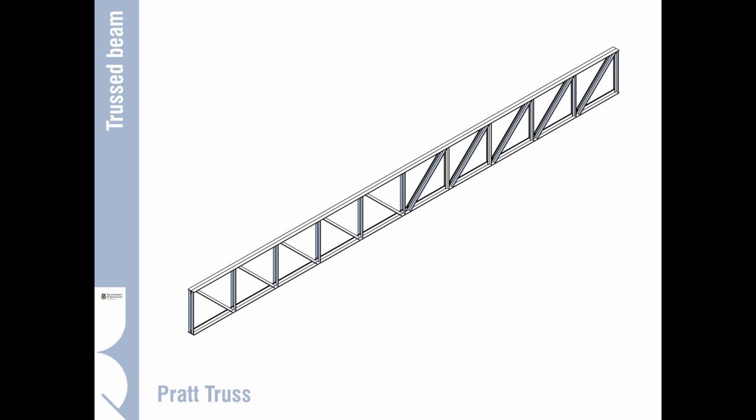As we saw in an earlier video on beam or truss elements at the Hawken building, the other thing that steel is very good for is just using off-the-shelf components to make lightweight web-type structures or trusses. Now there's quite a lot of examples of flat trusses that are very efficient with the use of steel, and often the use of equal angles paired up is a very simple and effective way of creating these elements.